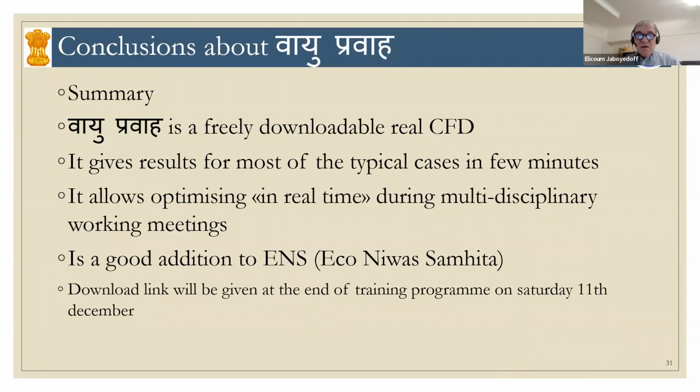So as a summary, we can say that Vayu Pravah is a freely downloadable real CFD, which people who register can get. It gives results for most of the typical block cases in a few minutes. It allows really optimizing in real time during multidisciplinary working meetings. If you think of architect, client, developer, and then engineers around that can discuss, or green building consultant who can discuss together on the different solutions and get very quickly some design direction and a basis for decision also.